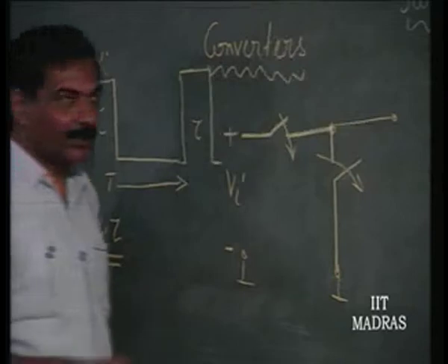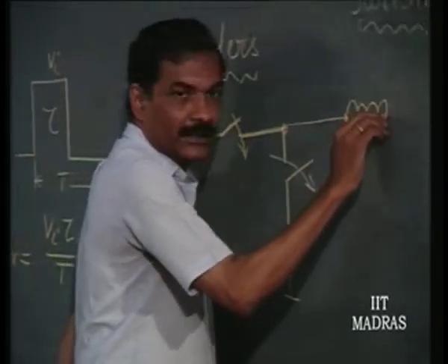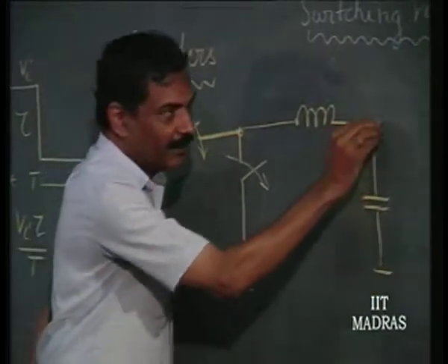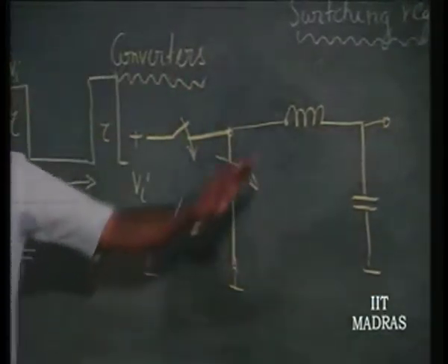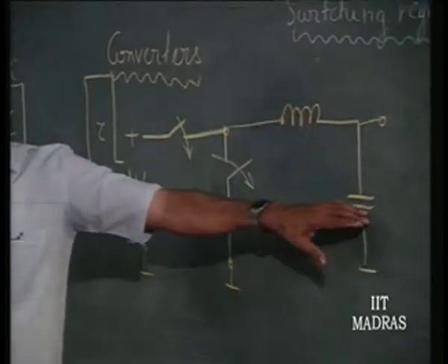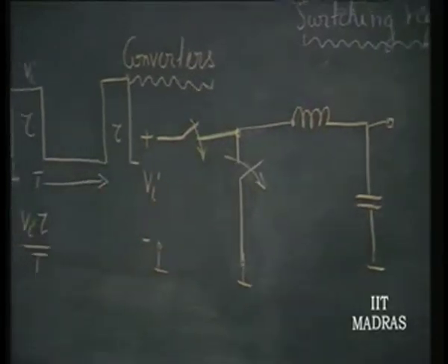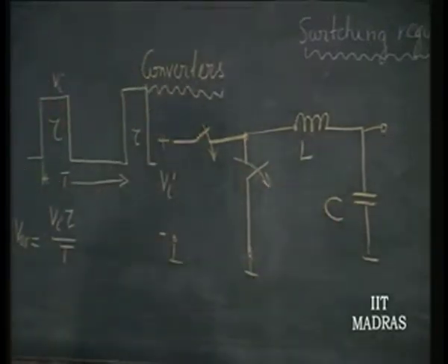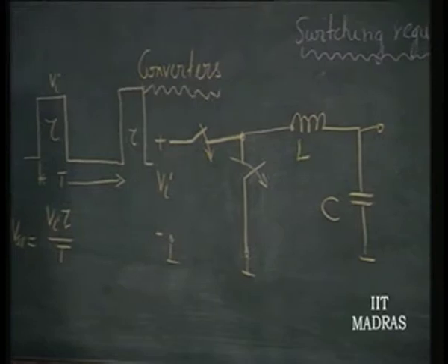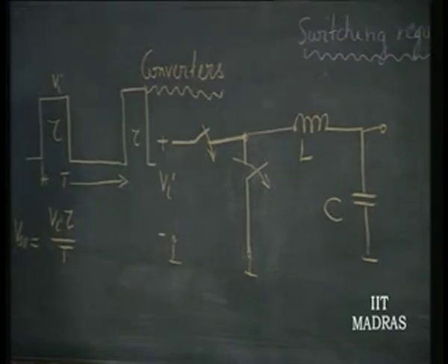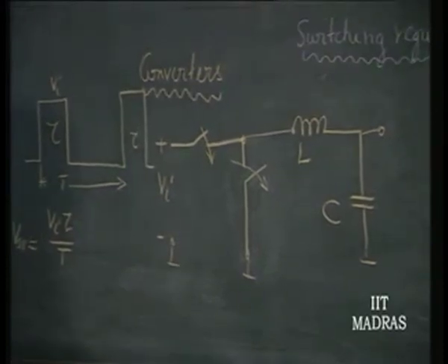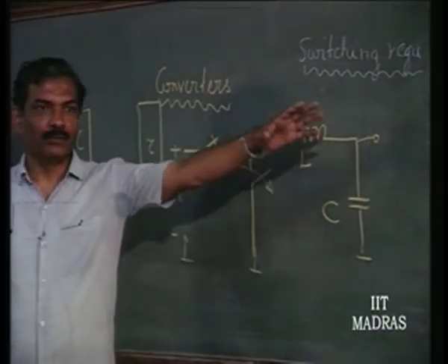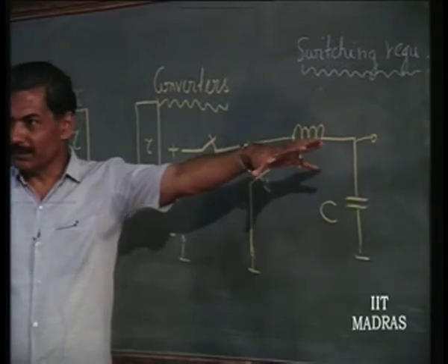So, what is a low pass filter? Put a series inductor and a capacitor. This is an efficient low pass filter. I can also build a filter using an R and a C, but again R is a dissipative element, so I do not want to use any dissipative element. Now, you see that this is the most efficient DC to DC converter one can think of. I have put only one LC filter block. If I put more, the filtering is going to be better, right.